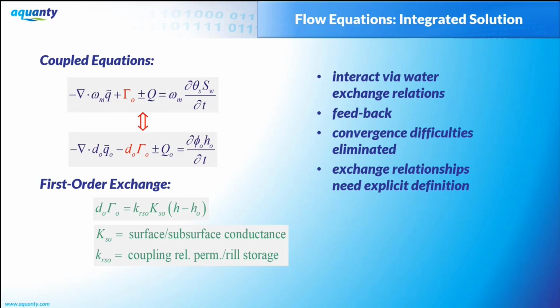So, equations. I'm not going to dwell on them. Most of you are familiar with equations, so you probably would be bored anyway. On the left, in the upper part, is the 3D form of Richards equation. There's actually another term added on the right-hand side, which includes specific storage. And at the bottom is the two-dimensional form of the diffusion wave equation. So it's like the St. Venant equations, but we threw out the momentum term in this case.